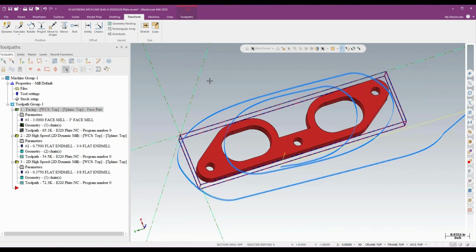You know, those are the ones you tend to use for export and import, ones you've actually proven out. That's a good toolpath. Why would you leave it trapped in another part file for eternity? So that's one way to do it. Once you get them imported in, you're chaining them, setting depths, and making whatever little adjustments you may have to make. But again, you're not starting from zero with every single toolpath.